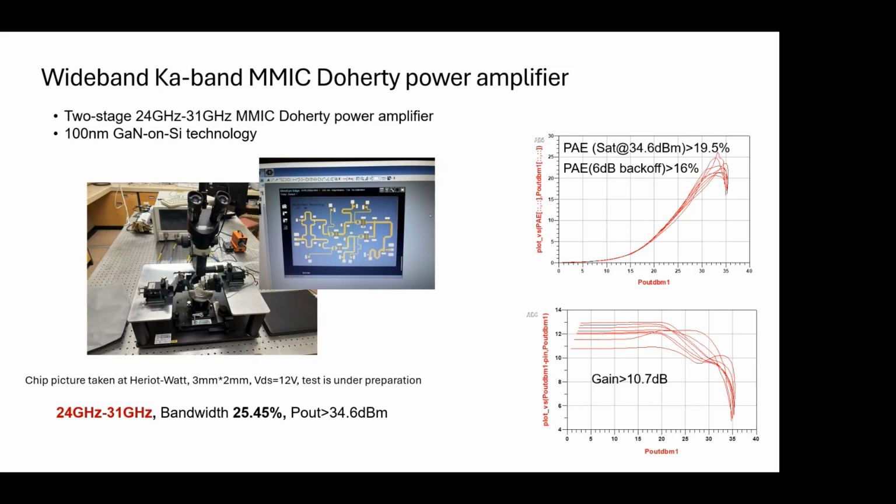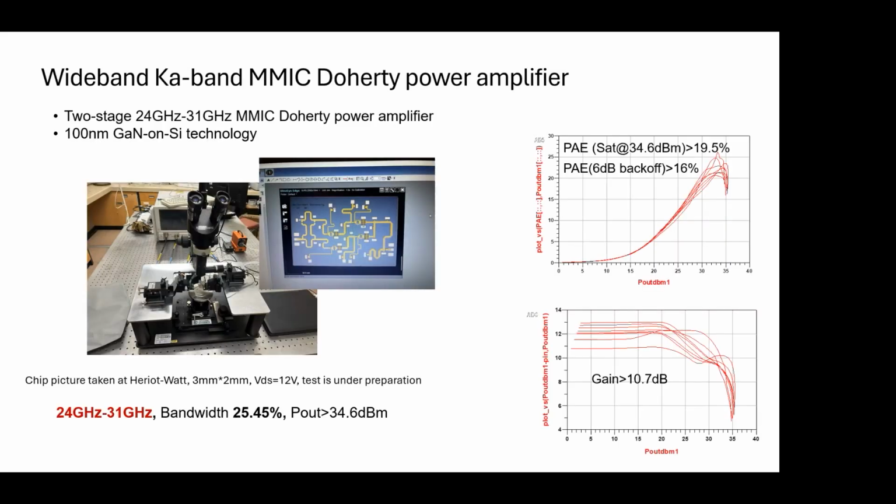Yeah. So for this wideband PA, the bandwidth is around 20%, 25%. Right? And I also want to introduce some recent work. When we design the PA, for example, for this chip, we have 30 variables inside. Because it's a wideband operation, we need to take all the things at different frequency levels into account, right?